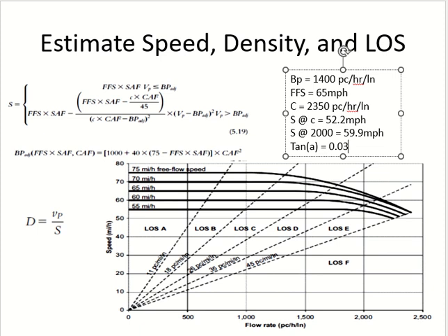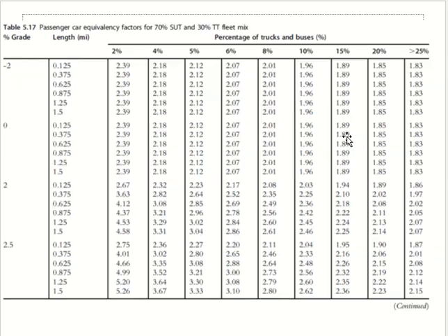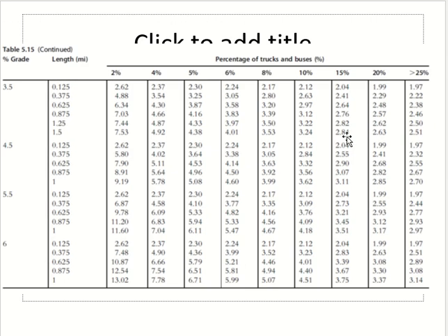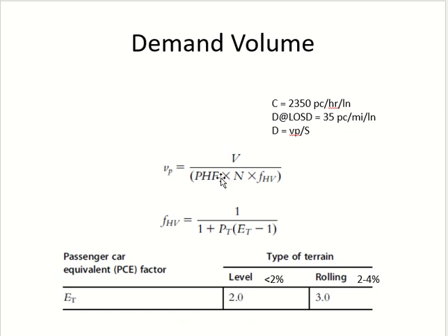So for example, this is a line, right? Let's say, I'm just giving an example, it's 1700. So 1700 is my Vp. I'm trying to find out the number of lanes. So now I will go here. I know peak hour factor. I know FHV. V is already given in the question. Now Vp from the graph. So I will find out the number of lanes. Clear?